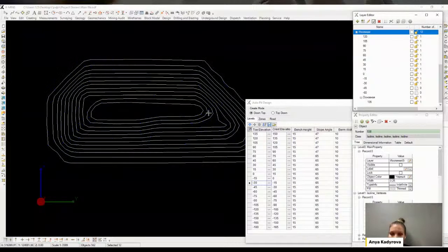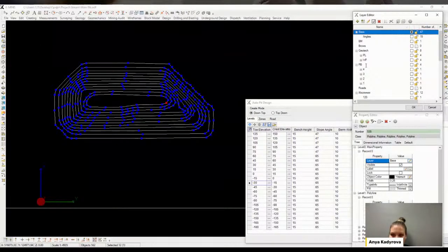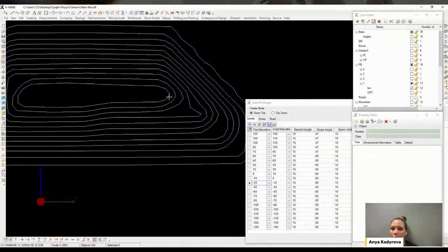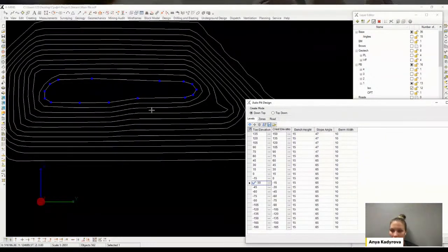So to start building, you must specify the basic closed contours from which the constructions will be performed. So specify the lower contour as a mark of minus 30 meters. And after pressing the calculate button, in the automatic mode, the edges will be rebuilt in accordance with the parameters specified in the main table, which must be filled in advance.